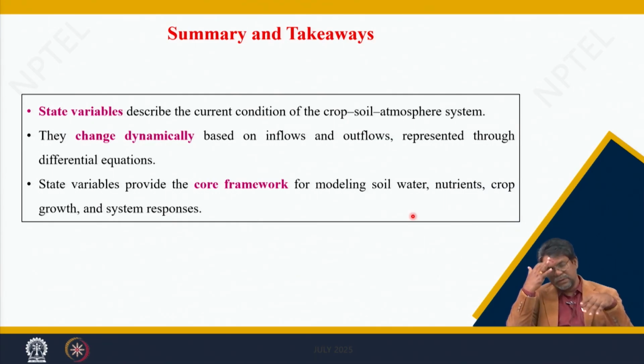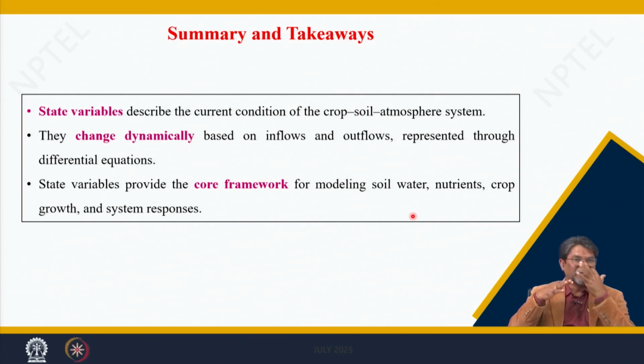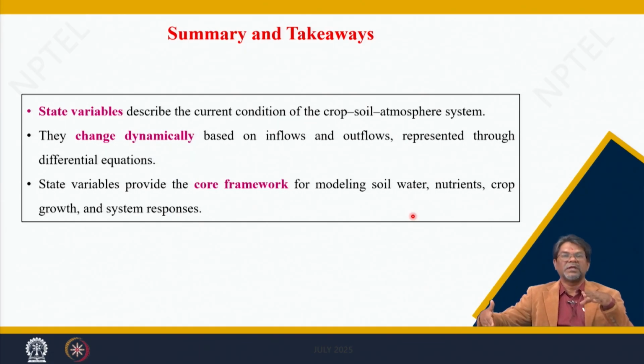This water tank example will give a brief understanding of how the state variables are represented, or how the processes in the model are represented. Suppose you run the model with an inflow of water and an outflow of water. Inflow is, say, 40 liters per hour, and outflow 30 liters per hour. If the data is available, run the model for 5 or 6 hours and you can see the change in volume of water in both the tanks. If you run for a certain period, the volume of water in tank 1 will come to 0 with time.